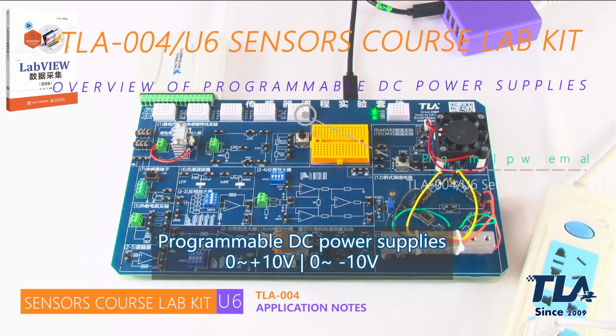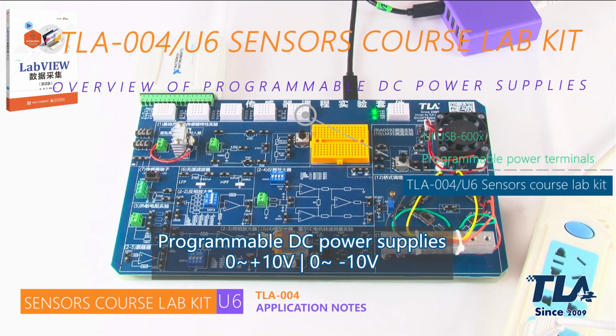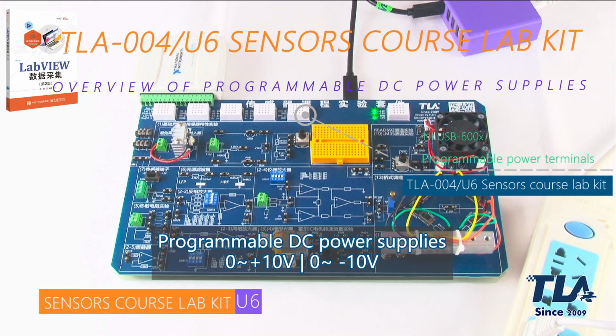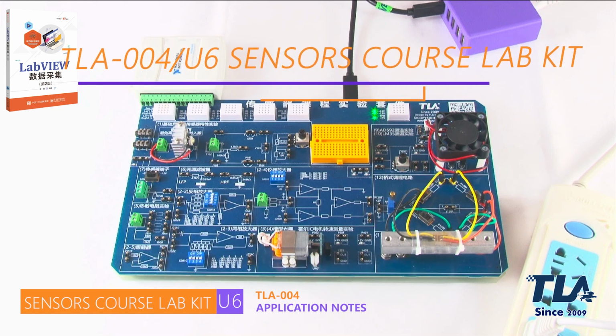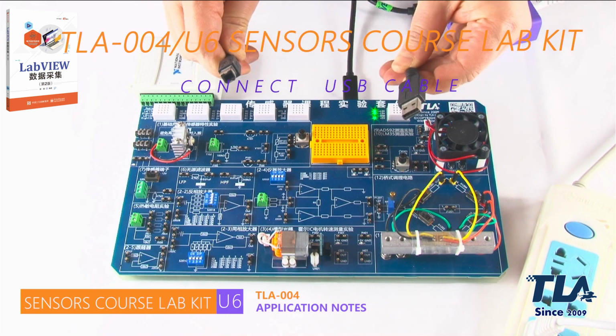The required power supply can be connected to the specific experimental circuit through wires. The terminal of the two-way programmable power supply is located on the left side of the power indicator light, that is, the fifth breadboard of the experimental suite board. The terminals are labeled VPS0 and VPS1 respectively, and the voltage output needs to be set in combination with the experimental software DAQ, where the DC voltage output ranges of the two programmable power supplies are 0 to +10V and 0 to -10V respectively. The maximum current driving capacity of each channel is 200 mA.